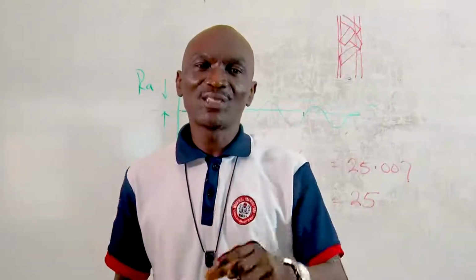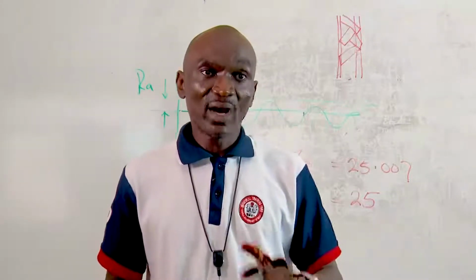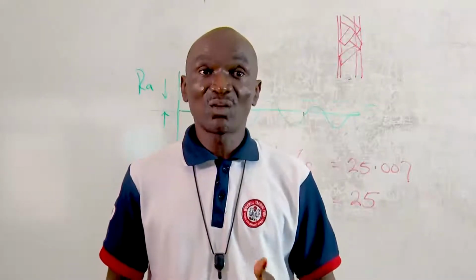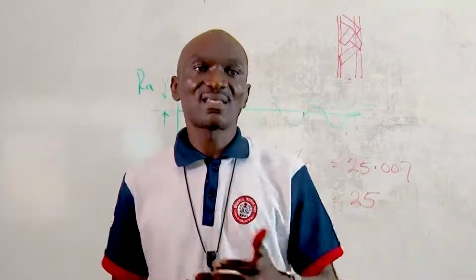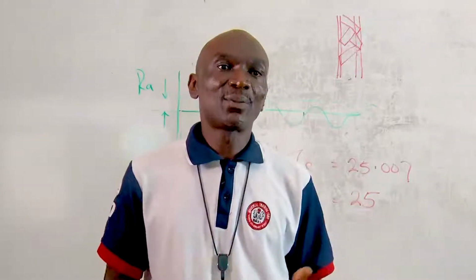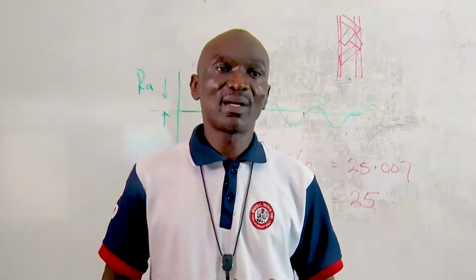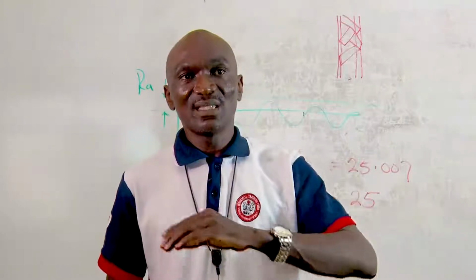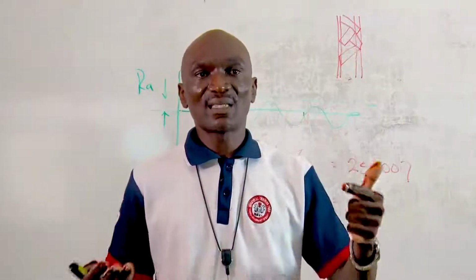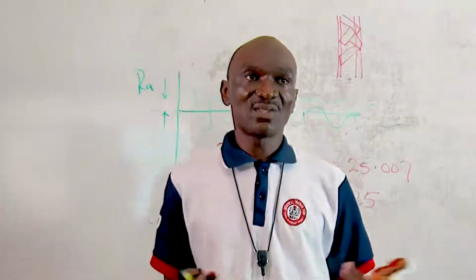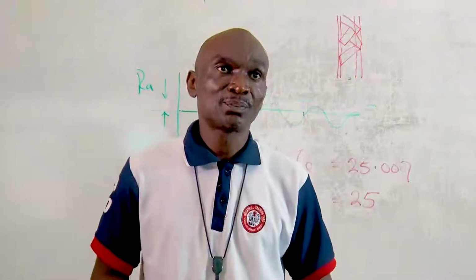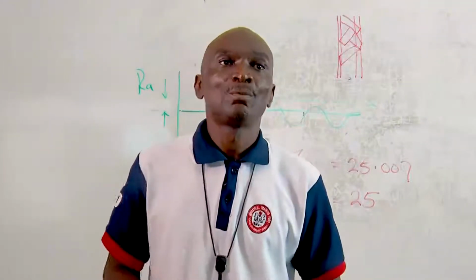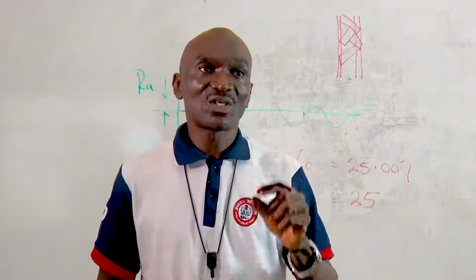The level of lubrication. Naturally, where there is adequate lubrication, you see that the wear rate is reduced. And where there's no adequate lubrication, the reverse is the case. In particular, by the process of deposition and wearing out of the boundary lubrication layer. So as the lubrication is taken off, there's metal-to-metal or material contact, direct contact between the contacting surfaces, and wear ensues. Now I want to look at the types and in particular what causes wear.